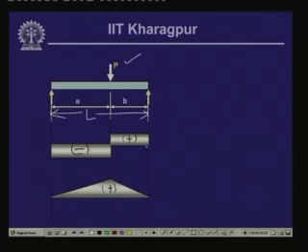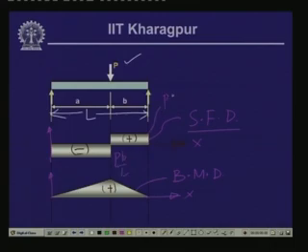So this we have taken as our abscissa, the direction of the beam, and these are the ordinate. This is the positive direction and this is the negative direction, and here again this is the length of the beam and this is the ordinate of the bending moment. So the diagram over the length of the beam which we get, this we call the bending moment BM diagram, and this we call the shear force diagram SFD. And as we have seen, the value of this is equal to the reactive force, which is P b by L, and the value of this here is P a by L.